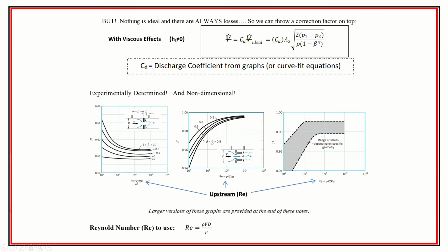So the larger the Reynolds number, the more the dynamic forces are overcoming the viscous forces. So really, with a high speed, we get a higher Reynolds number. And so you can see that these factors right here have a sort of a trend that are kind of different for the orifice versus the nozzle.